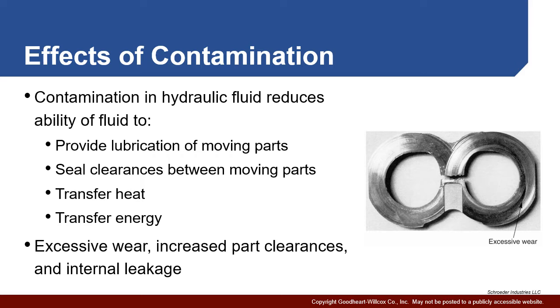Keep in mind, as they wear, the seals break down, and those clearances will potentially get larger, which allows more leakage. Contaminated fluid is not nearly as effective in transferring heat and energy. And then, of course, the wear in functional parts eventually causes problems in the functioning of your circuit itself.